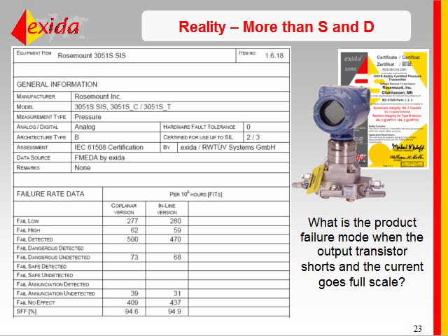I would like to comment that in reality, when you convert functional failure modes of a component into IEC 61508 categories, sometimes you can't determine whether a functional failure mode is safe or dangerous unless you know the application. So that classification has to be done by the system designer.